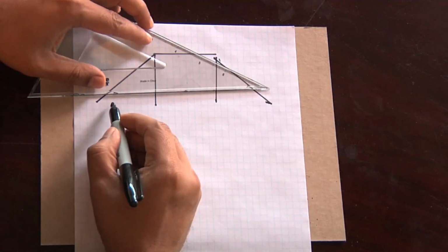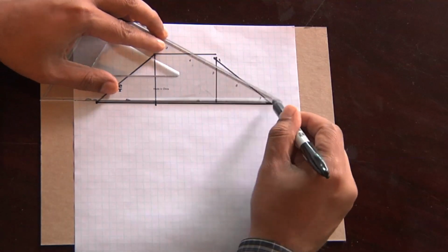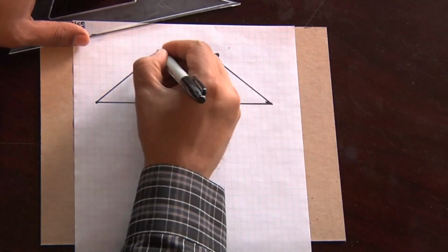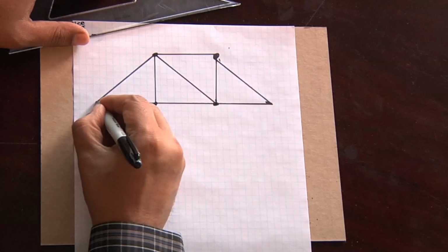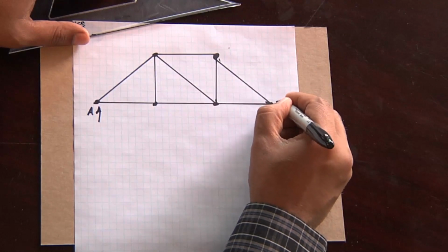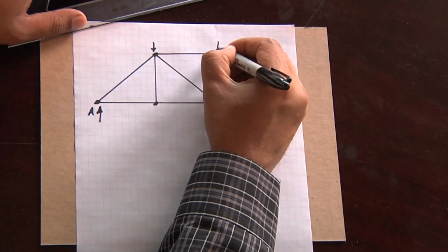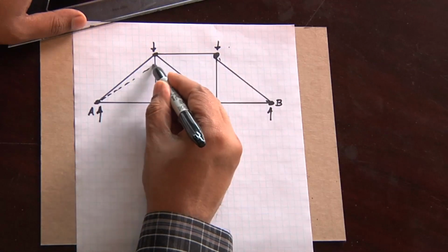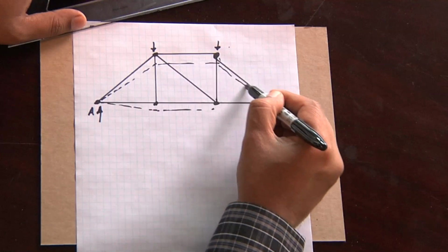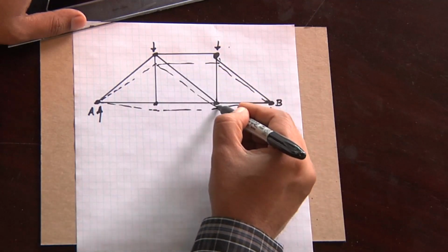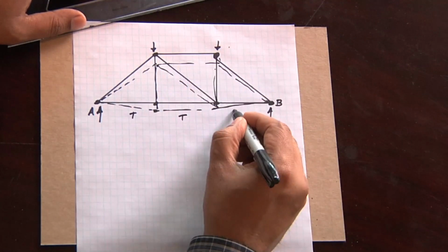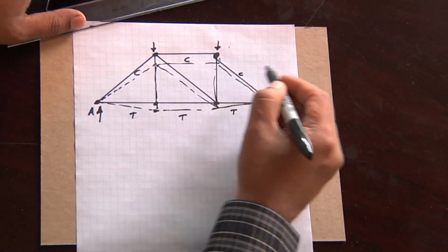Here's a truss, a very simple truss. These are used in bridges and in roof structures all the time. And all of these joints are pinned. So if I have my truss supported here at two endpoints and I apply a load, the deflected shape of the truss will look something like this. It will bend downward just like a beam, and the bottom members will go into tension. The top chords will go into compression.